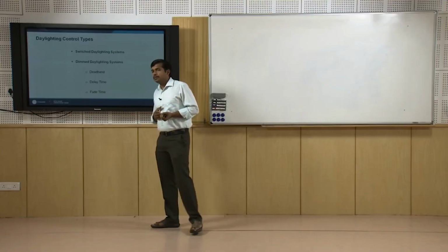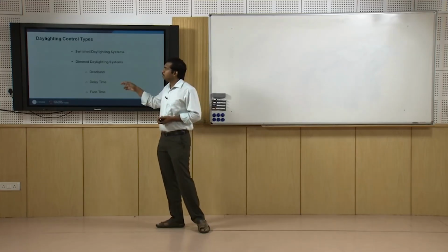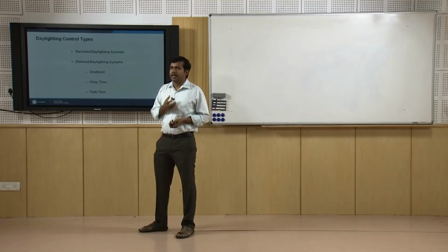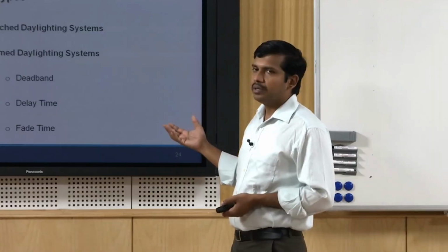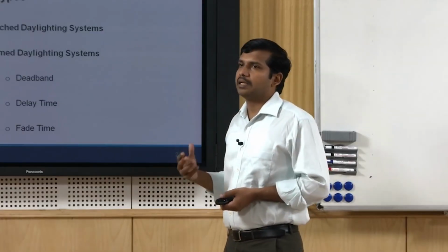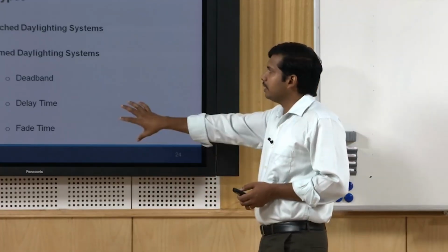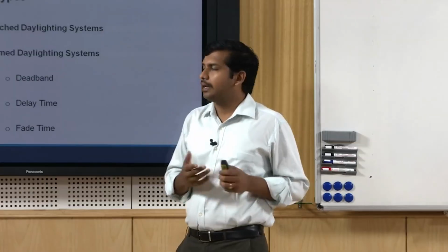So there are two components we have to keep in mind. One is effective daylight harnessing or harvesting, and second is the use of control systems, which is also crucial. The type of control which we are tagging to the actual artificial lighting will also determine the efficiency or energy performance of your whole system, that actually determines your daylight efficiency and the reduction in artificial lighting energy.